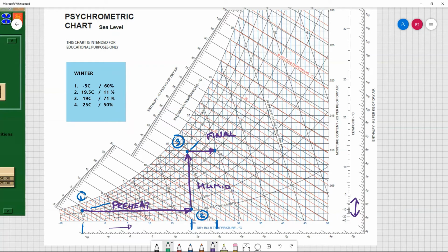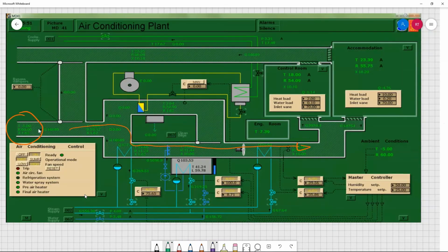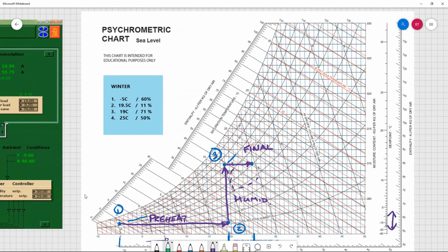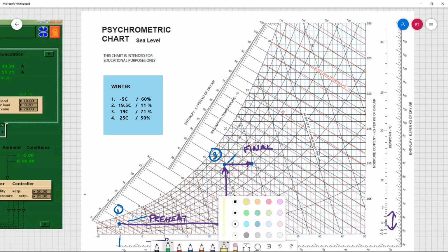And in general, on this diagram, I'm trying to target essentially an area that's, I don't know, say somewhere in this range as my comfort conditions. So say 20 to 25 degrees and 40 to 60% humidity. So bringing me into that comfort condition.